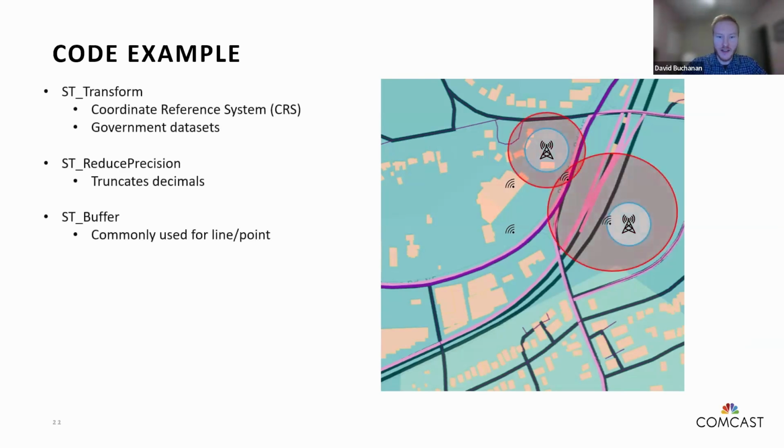The next step, in this case, we're utilizing an ST_Buffer operation. We have the cell sites within the slides, and maybe the first ring that's light blue is 5G. 5G uses higher frequencies, can't travel as far, and so that's when you're in 5G coverage. The red buffer is showing you 4G LTE, so you're still going to have connectivity, but maybe you're not getting those really high speeds. So also, you have the network infrastructure. ST_Buffer is something I use all the time. It's a fantastic operation.